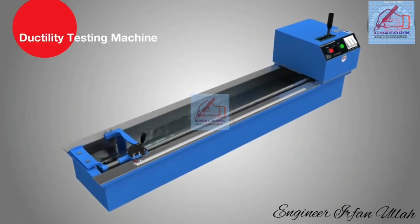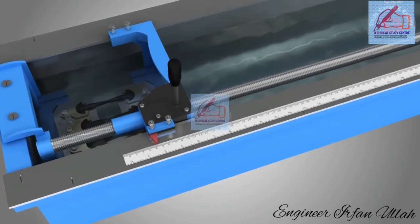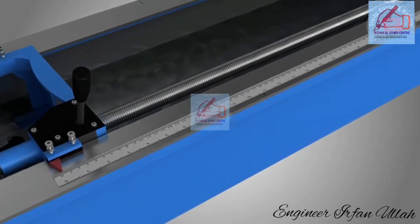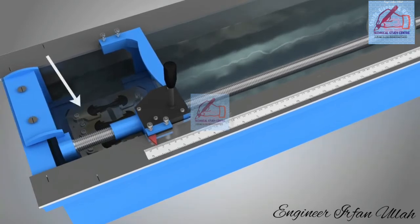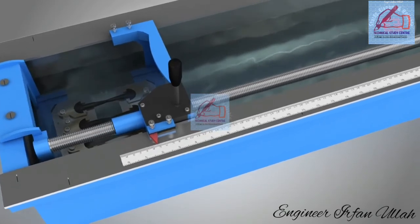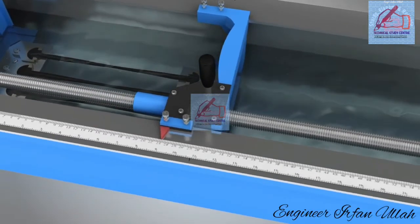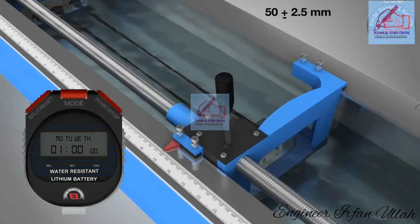Ductility testing machine. This apparatus is a constant water bath type with a pulling device at a pre-calibrated constant speed of 50 mm per minute and 10 mm per minute. The central rod of the machine is threaded and through a gear system provides movement to the ductility molds, the clip of which is fixed at one end and the second clip is stretching the thread of bitumen binder away from the first clip. 2 clips are thus pulled apart horizontally at a uniform speed of 50 mm per minute, plus or minus 2.5